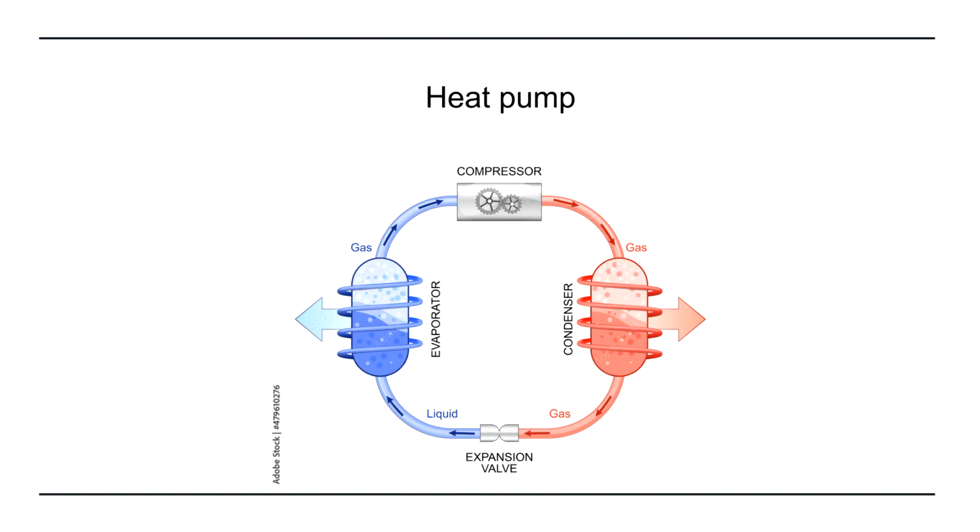Condenser then rejects the heat and returns to a liquid state, but it's at a higher temperature until it goes through the expansion valve or a metering device, which then turns it back to a liquid, and then back to the evaporator where the liquid then becomes superheated vapor again at a low temperature, and works our way around.